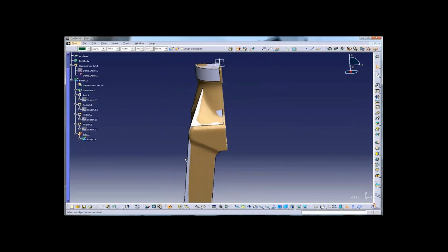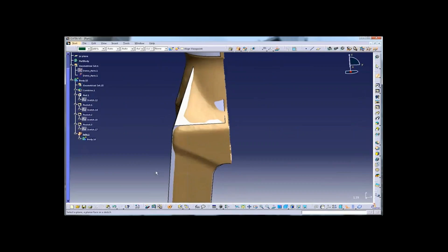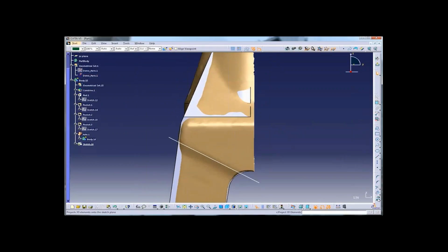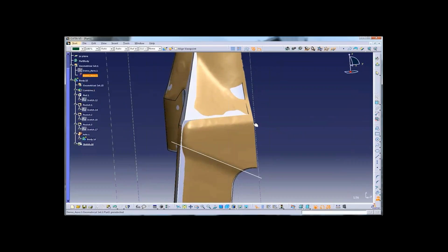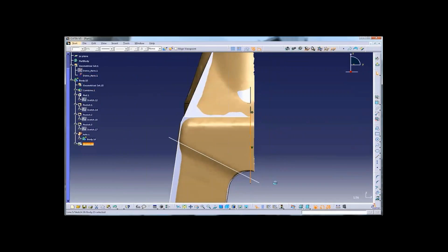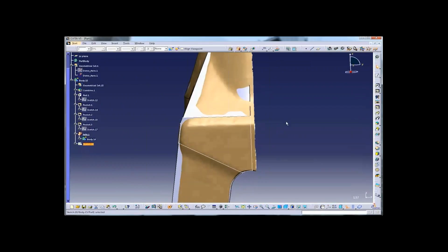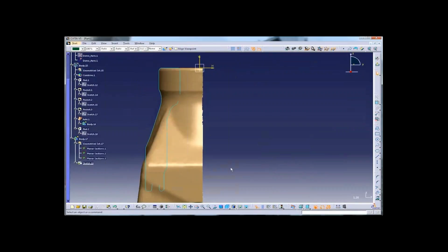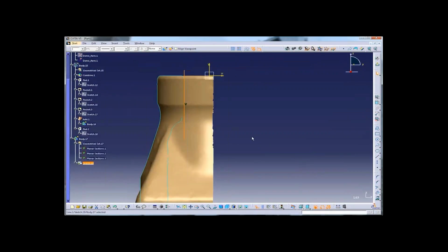At the top, we can see another protrusion there. So I'm going to create another sketch once more in order to just add some material to our CAD model. Trimming my profiles, getting a nice sketch there. Here it is. Adjust the height, and that's it.